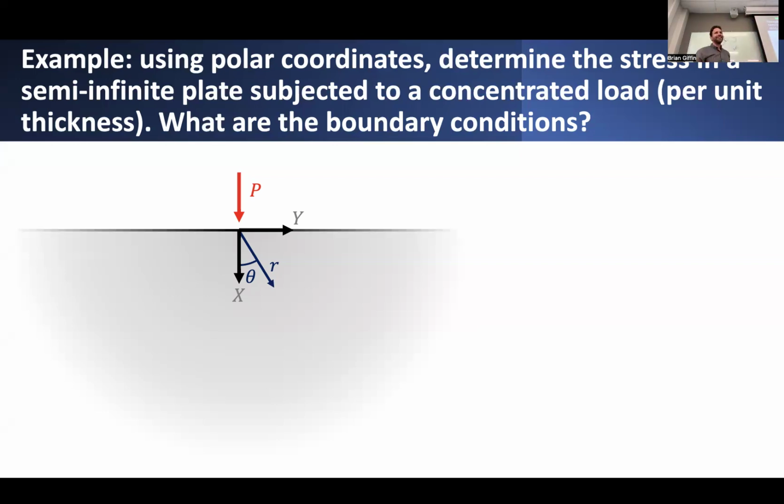Yeah, it would have to be infinite, because technically speaking, if I'm applying it at a point, I'm applying a force per unit of zero area, which by our definition of stress would imply that the stress would blow up. It has to achieve an infinite value.